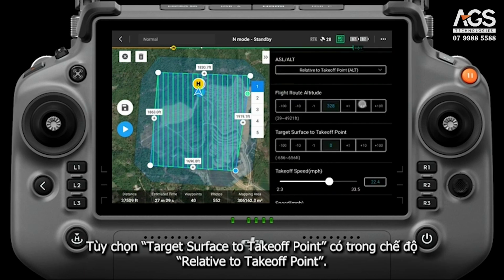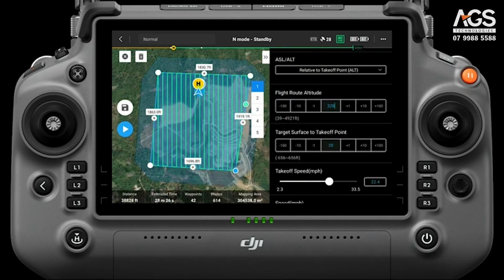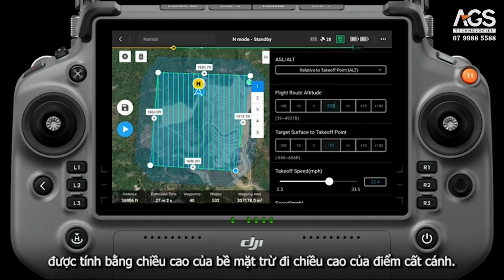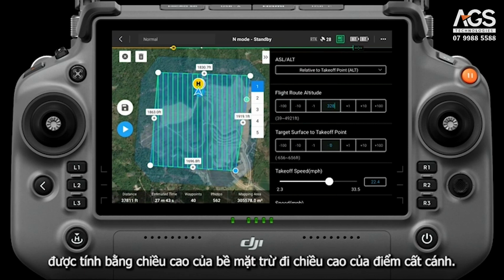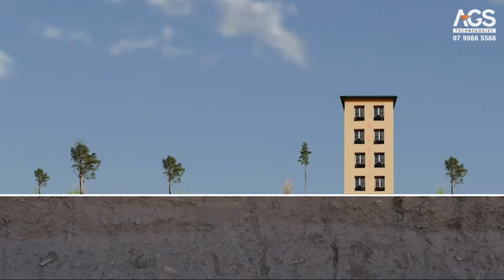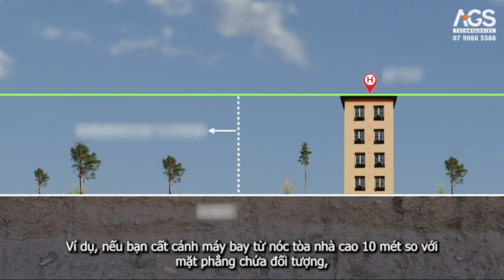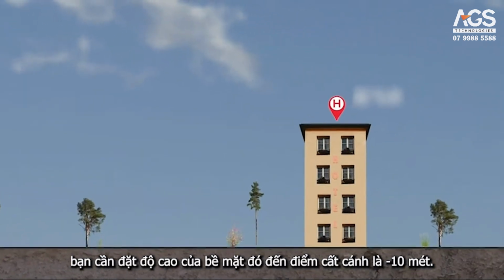The Target surface to takeoff point option appears in relative to takeoff point mode. The height of the target surface to takeoff point is equal to the height of the target surface minus the height of the takeoff point. For example, if you take off from the roof of a building 10 meters high above the target surface, you need to set the height of the target surface to takeoff point to minus 10 meters.